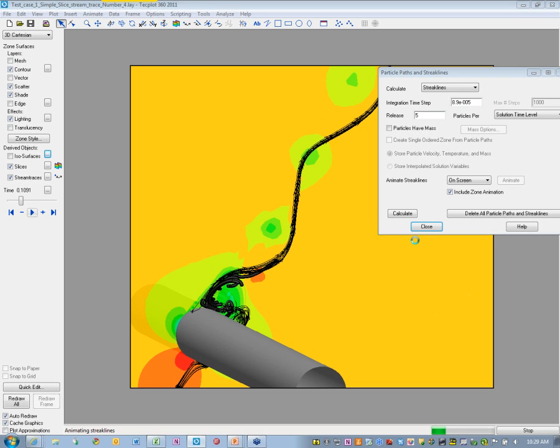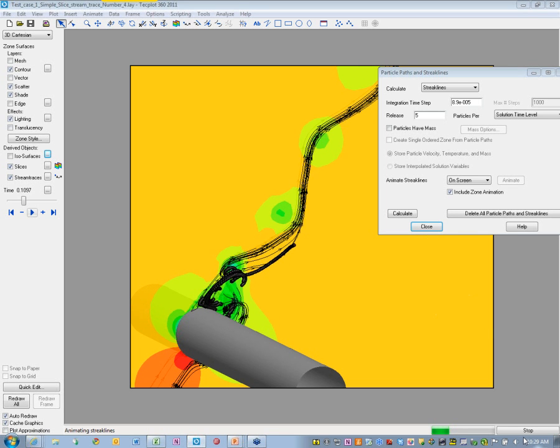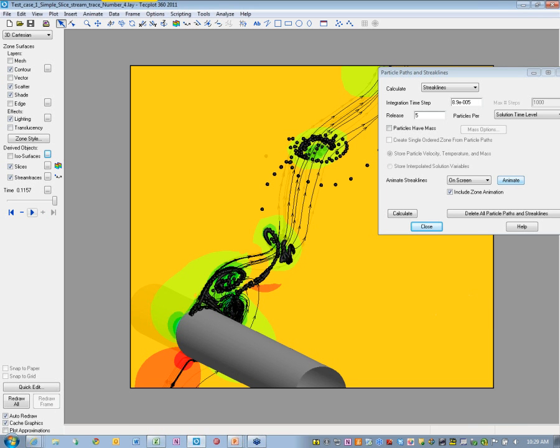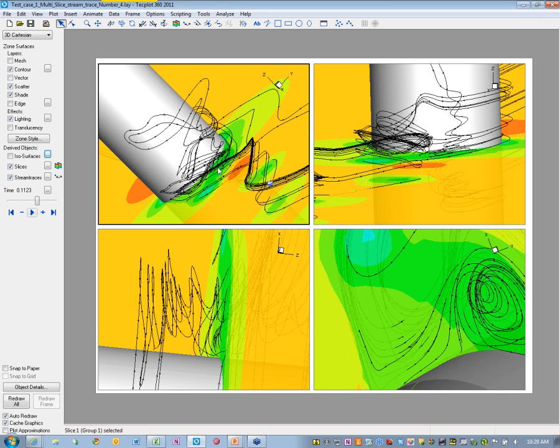So when it comes to presenting this information, let's assume for the sake of argument you were more interested in the Streamlines versus the Streaklines. I'll go ahead and stop this. You may want to look at multiple views of that shedding to get an understanding of what's going on. So I'm just going to change this from one frame to a series of frames. Now what we're looking at is kind of edge on. These aren't exactly principal views, they are skewed, but we're looking at 4 views of that same cylinder where we're looking at the streamlines, and I'll go ahead and animate this as well.